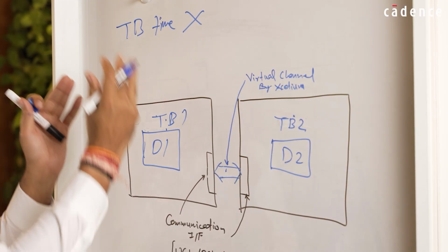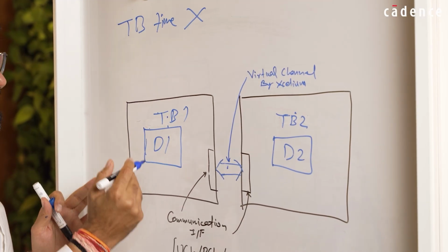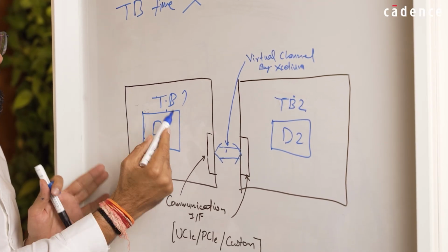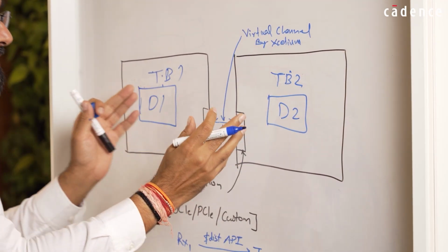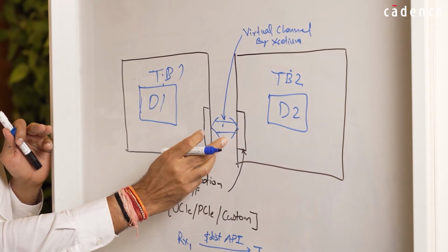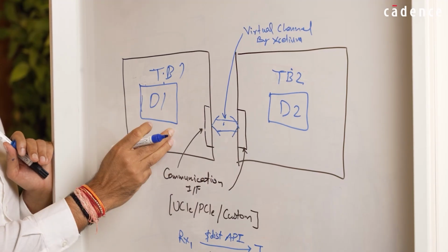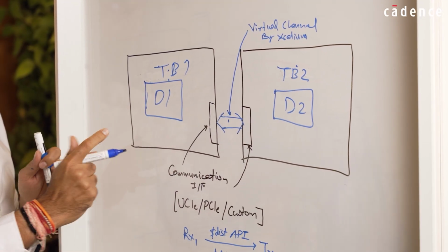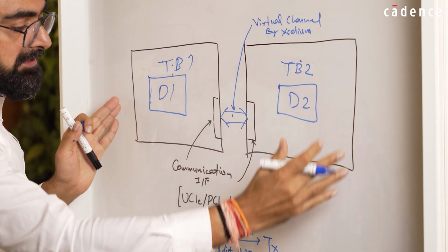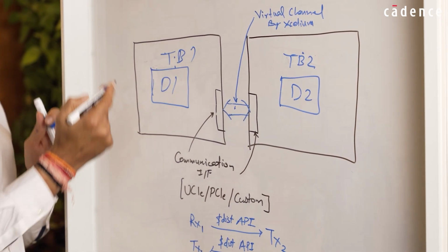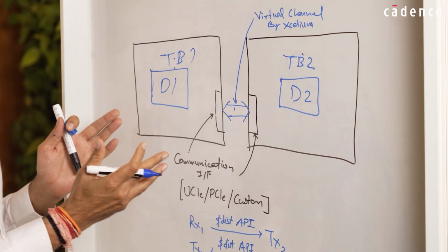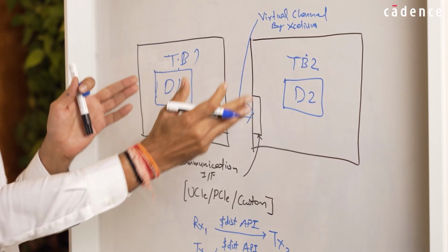The second thing we talked about was performance, because earlier you were integrating multiple dies together in one snapshot, then running the test case. Here, your test cases are running in distributed simulation mode, integrated by the tool together through these virtual channels, and yet the tool gives you the full experience with LRM compliant connections, so your system simulation works as it is, but in distributed simulation mode.